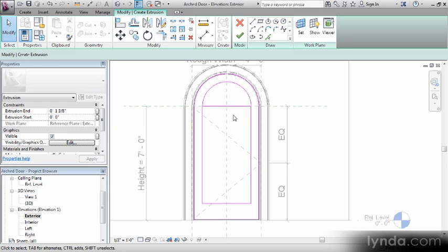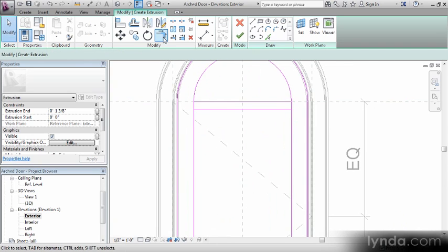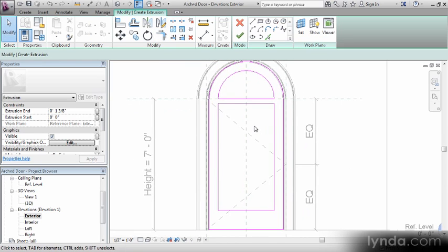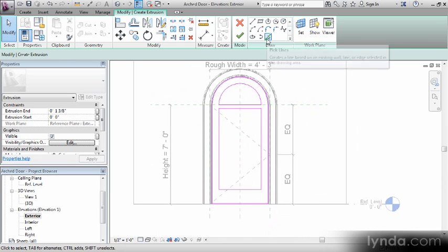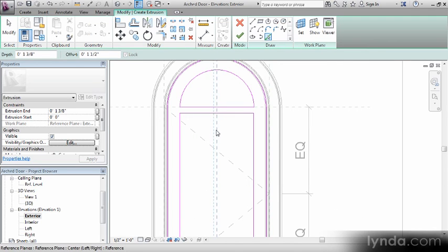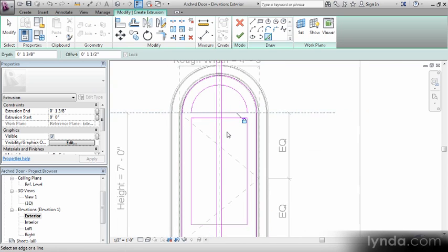Let's offset this down 3 inches. On the Draw panel, click Pick Lines. Let's offset 3 inches. Hit Escape a couple times. Click Trim Extend the Corner. Let's clean that up. Hit Escape a couple times. Now let's get a center one going. On the Draw panel, click the Pick Lines button. Let's offset this one 1.5 inches. Let's go to either side. And we have it.